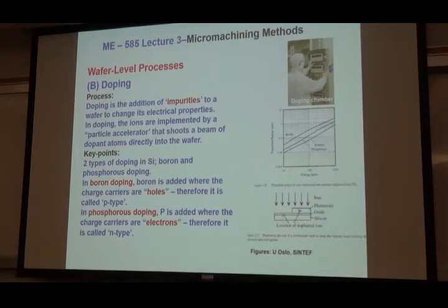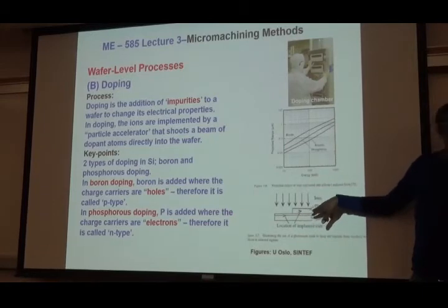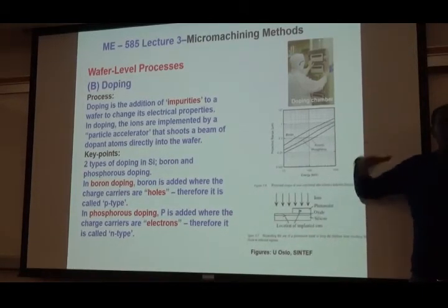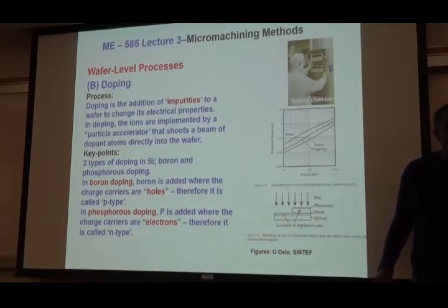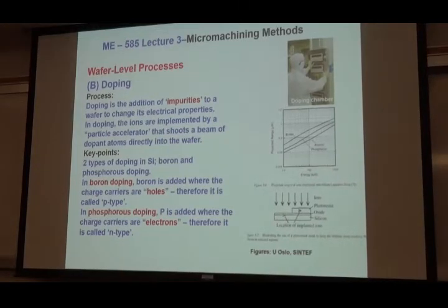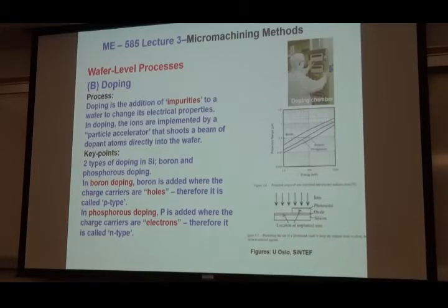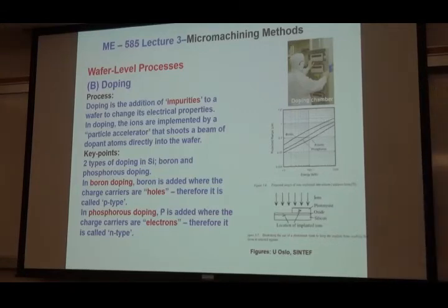So for that, I'm going to do lithography, but I'll explain that later on. Because essentially what I'm going to do is, I'm going to cover areas that need to be protected by this photoresist. But areas where I really want them to be doped with phosphorus, I'm going to keep them open. Okay? So I have an open area, it comes in, you bombard it for, again, how thick you want it is going to be determined by the time. Okay? And I don't have the relationship here, but it's a function of time. Okay? So doping chamber, pass your gas, so phosphorus is going to be in terms of gas.